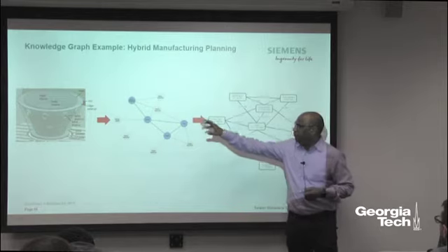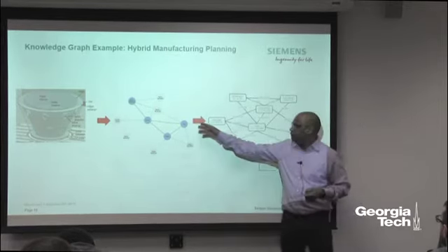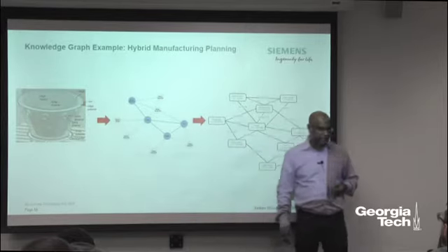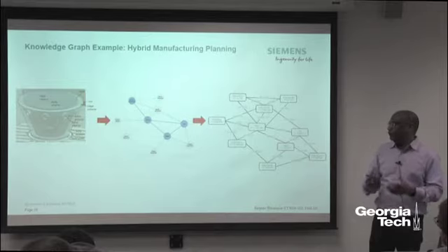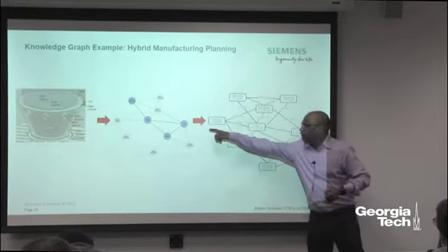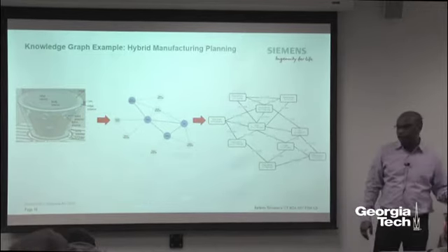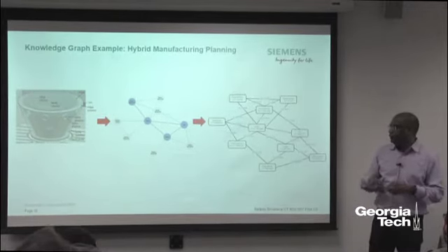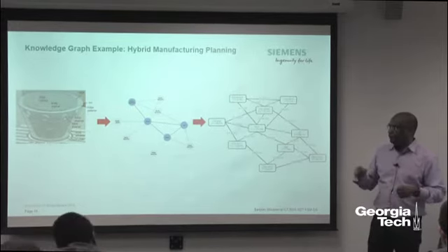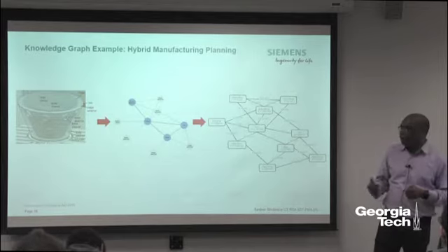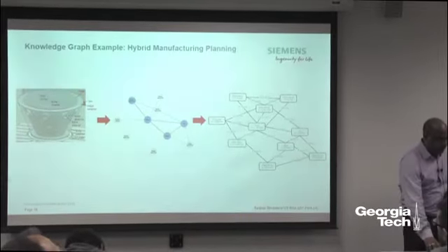So we embed the design into a kind of design graph, where each node is basically the manufacturing feature and each edge is a surface, and then utilize this graph to come up with the most optimal operation, because each of those manufacturing features can be done additively as well as subtractively, and there's a certain cost associated with it. So we use these kinds of graphs to explore what set or sequence of operations leads to the least amount of cost, and are the solution for manufacturing these kinds of parts.